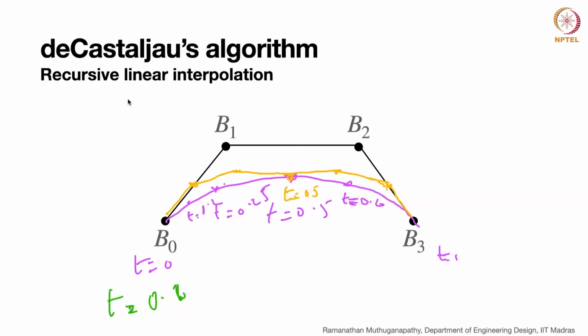Gaurav, are you seeing this picture? You can see that if you divide it here, this subset will actually be another Bezier curve and this subset another Bezier curve. You can see these control polygon points come directly out of the de Casteljau algorithm. And you can split the curve. This holds good for any parameter t. You can split this curve and get Bezier control points using the de Casteljau algorithm itself.